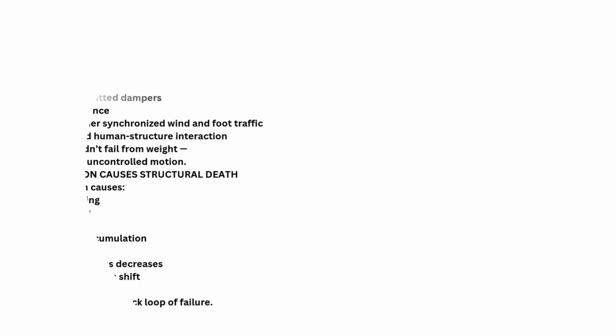5. How vibration causes structural death. Repeated motion causes fatigue, cracking, bolt loosening, weld failure, cable stress accumulation. Over time, structural stiffness decreases, natural frequencies shift, vibrations worsen. The bridge enters a feedback loop of failure.